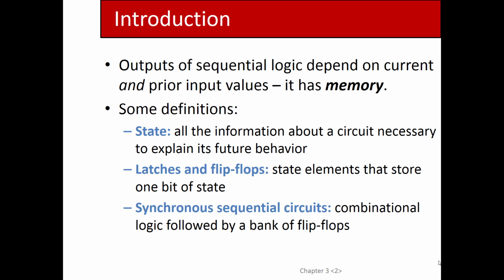We'll also talk about latches and flip-flops. I think you might have covered this a little bit in 211, but as I understand it, not very thoroughly. A latch and a flip-flop is the little primitive component that actually stores the memory in a sequential logic circuit. Registers also come up. Registers are where you have multiple flip-flops in parallel that hold a multi-bit value.